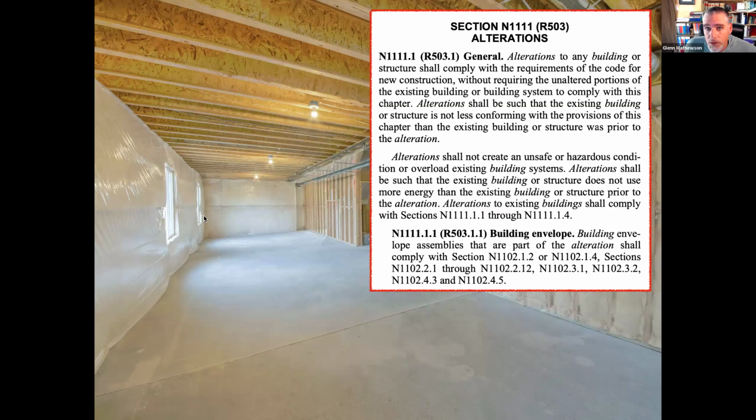What about this basement, though? Look, there's no insulation in the floor. So even though it's an unfinished basement, that does not mean it's not conditioned. This is still a conditioned space. And so finishing this basement does not change it from an unconditioned space to a conditioned space. And so it does not kick in the same requirements we saw for the garage, where I would have to furr out the walls or thicken the insulation. This basement is already insulated.